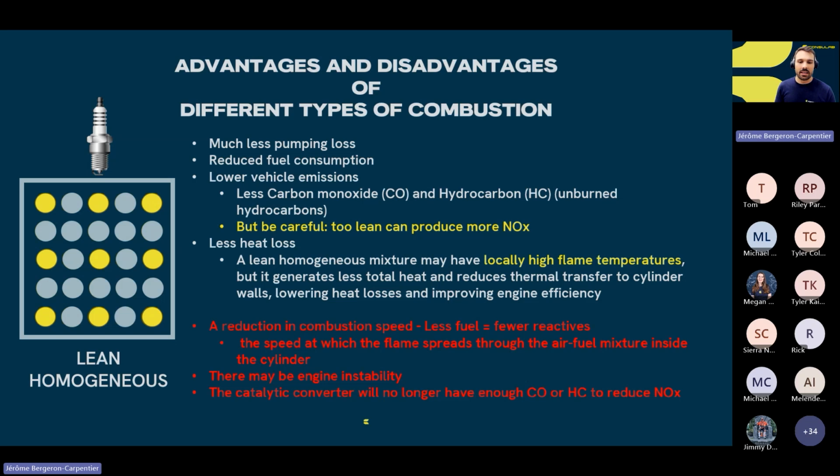The catalytic converter, we no longer have enough CO or HC to reduce the NOx, so that's the thing. We do have a lot of air, but because we don't have carbon monoxide or hydrocarbons, we cannot split those molecules and treat the NOx and generate some H2O, for example, and carbon dioxide.